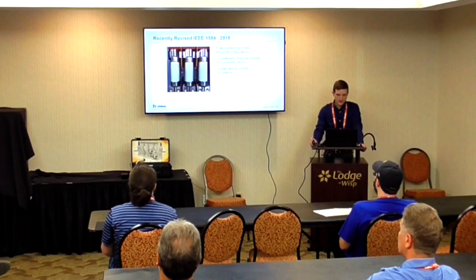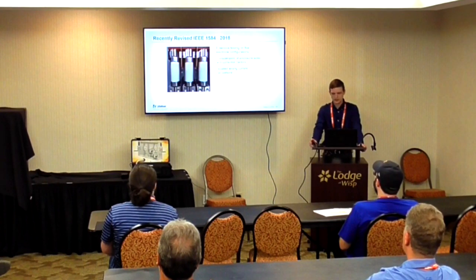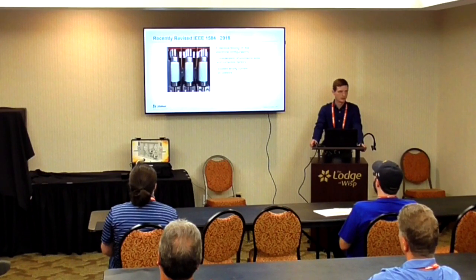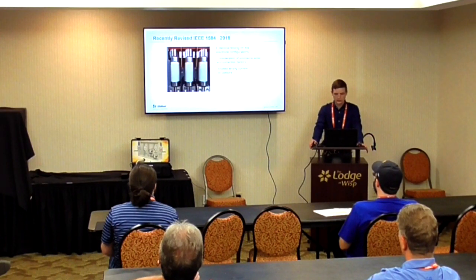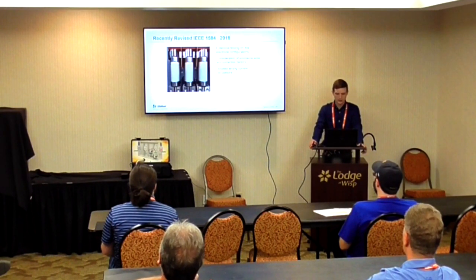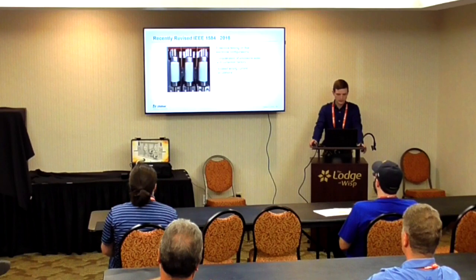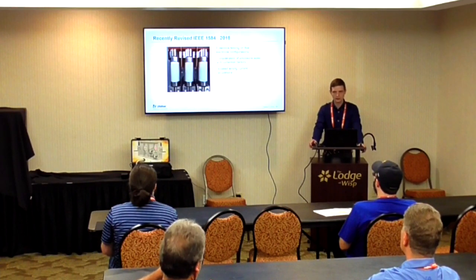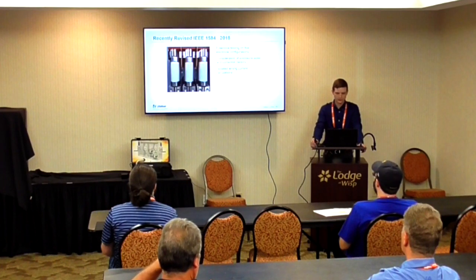The enclosure correction factor also exists in here now. Standard opening is 20 inch by 20 inch. The maximum value is typically 49 inch by 49 inch. It's not completely based on the volume. There is a trend for larger openings: you'll have a larger incident energy, but the trend is actually reversed for a shallow enclosure. The smaller opening would be better for a shallow enclosure.